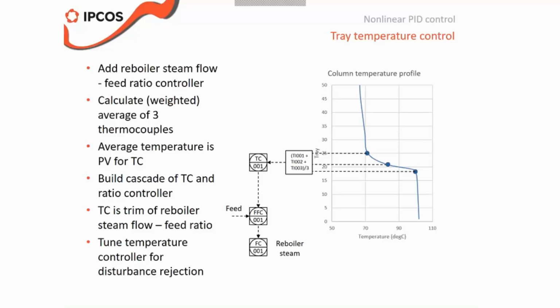So for valve and pH example, a characterization block is used, and why not also use a characterization block for the temperature control? That's a good question, and the main reason is that for the valve characteristic, the assumption is the flow to valve characteristic will not change that much depending on the process condition. It has kind of a fixed shape, you would say. Well, if I look at the temperature profile in the column, that might change depending on the separation index.